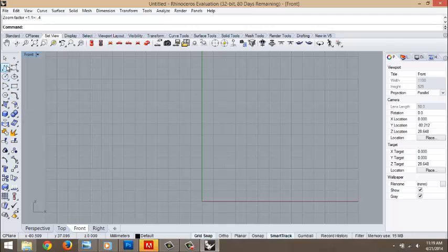So I'm going to come over here to begin drawing a line segment. Now I can click on the box, but I need to click on the lower right corner of that box down here to pick the right line. And I want to do a polyline or line segments, that's plural. I click that. Now move my cursor down here to that intersection of the green and red line. Click once, and now I'm going to go out.